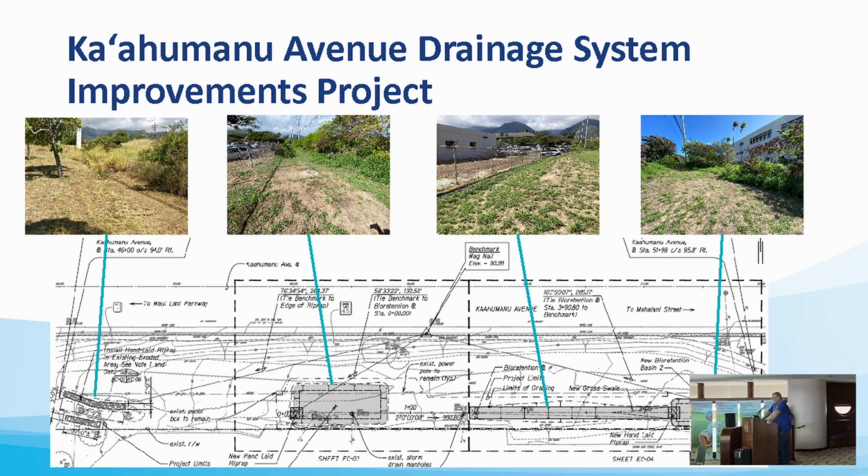Scope of work includes site grading, retrofit of existing drainage structures, construction of bioretention basins and grass swale, installation of a temporary irrigation system, soil amendments, and landscape. On the left of this plan view, it shows the riprap aprons used to slow the velocity of the runoff waters as it enters the site to help control erosion and minimize sand and silt from entering basin number 1. Then the grass swale leading to basin number 2. During intense rain events, the excess stormwater flow will enter the graded inlets and into the MS4.